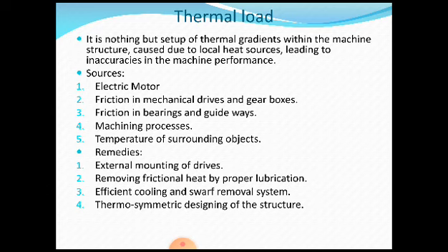So whatever thermal load is coming into the machine structure of the CNC can be prevented by external mounting of the drives. That means especially the motors: instead of mounting them within the CNC machine housing itself, it is possible, by changing the design of the CNC machine, to have those drives or motors mounted outside the CNC machine itself.